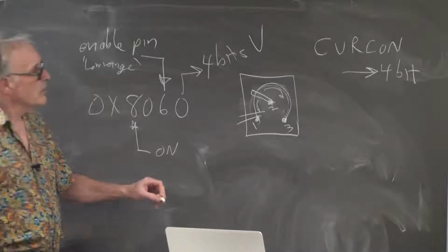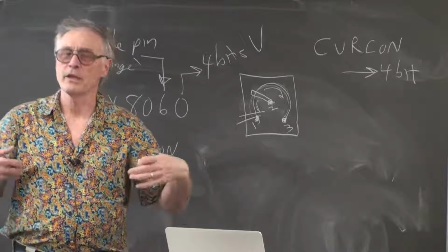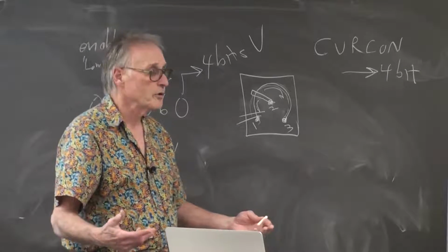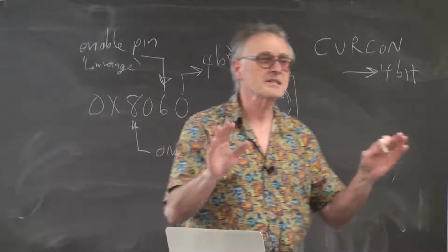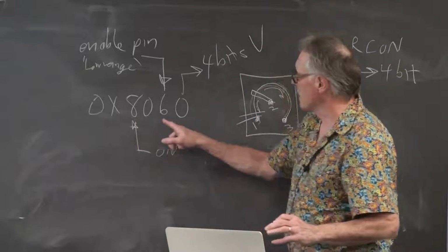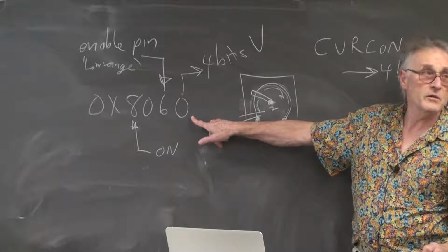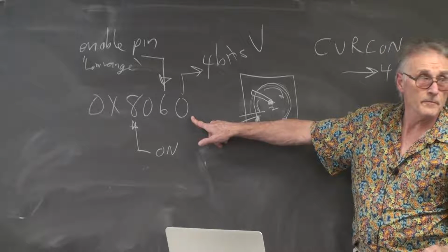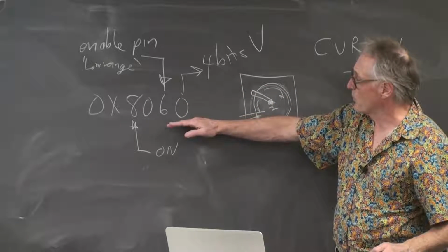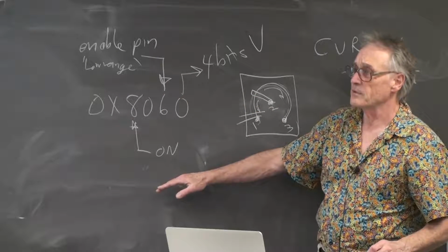So in the table that you build to spit out of the I/O port, out of the VREF port, you have to build a 16-bit table whose top 12 bits are a constant and whose low 4 bits are the signal that you want to send. So the table is going to be a very boring table of 0860 and then 4-bit values.